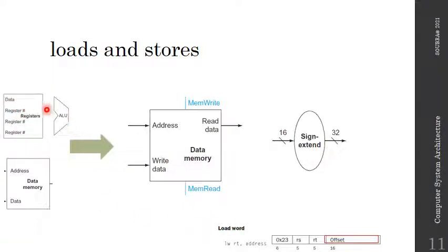If I'm doing that, this means that I'm feeding the ALU the 32 bits of the base. However, here the offset is not 32, it's 16. So that means that my implementation is not generic anymore, because I'll need a special path for the 16. Well, no. I'm going to try and deal with it in a different way.